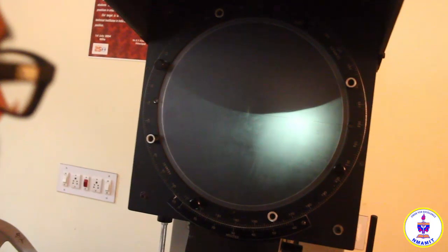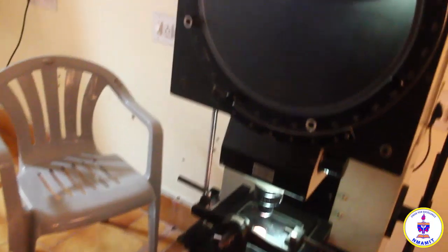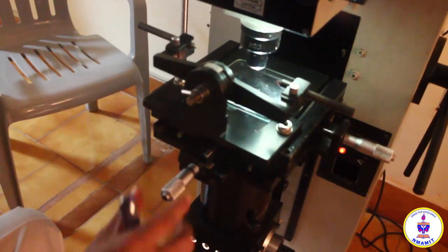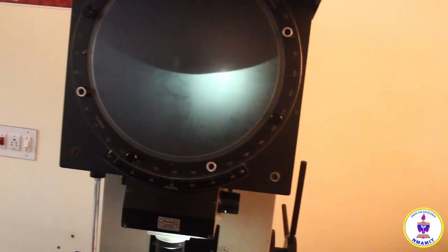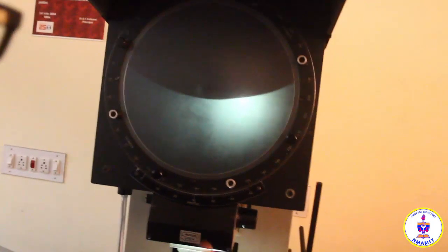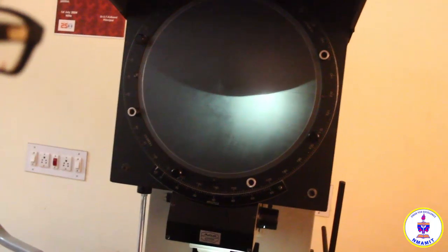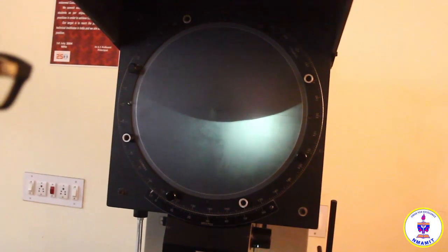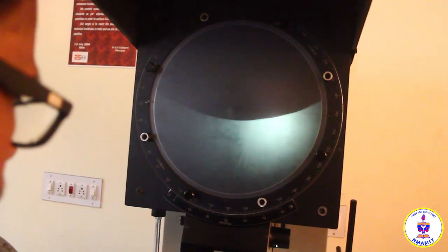Take the first reading corresponding to this position on the micrometer. So this crosswise movement micrometer here, take one reading here. Move the shadow downwards to the next position here and take the micrometer reading as the second reading here. So this can be moved to any depth. So actually we are making a measurement on a chord, the length of the chord and its height from the curve.